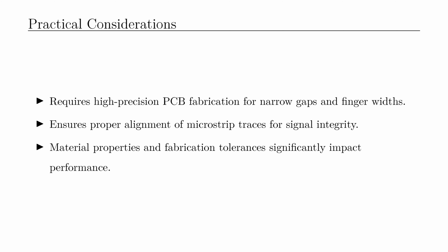In conclusion, the Lange coupler-based balun successfully achieves its theoretical objectives of balanced output, phase splitting, and power division. The scattering parameters S21 and S31 validate its performance. Tools like Keysight Genesys facilitate accurate implementation, making this balun design invaluable in RF and microwave systems.